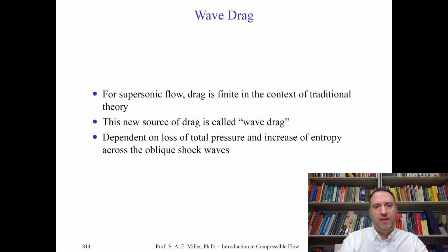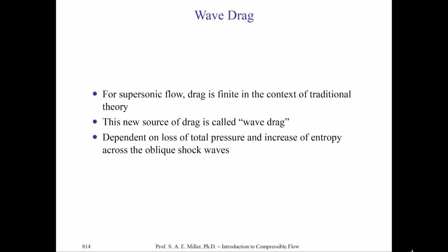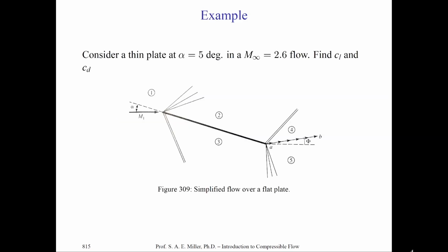Now remember, the wave drag will be dependent on the total pressure and increase of entropy across the oblique shock waves mainly. You can see it's really the integration of the static pressure. But of course, we can see that the wave drag goes as total pressure and entropy increase, which is the losses in the flow. Let's look at one particular example.